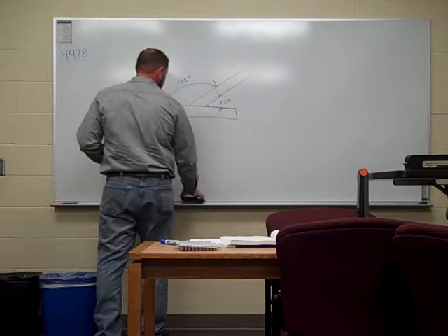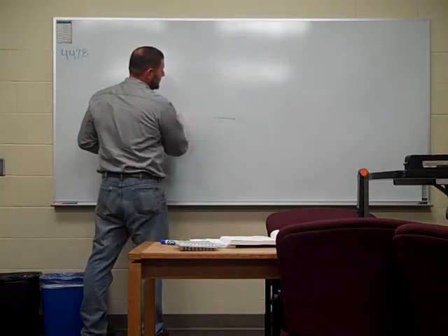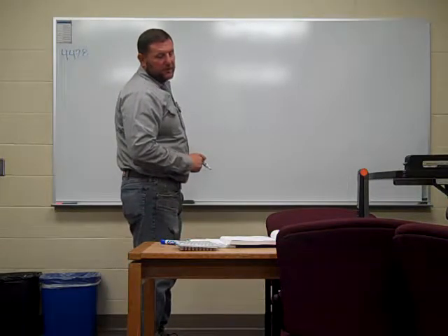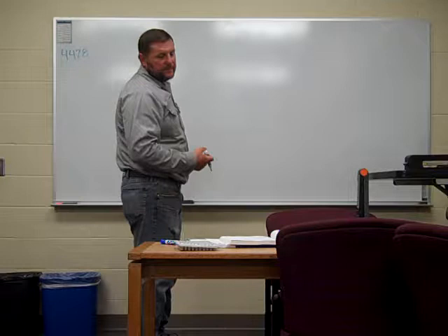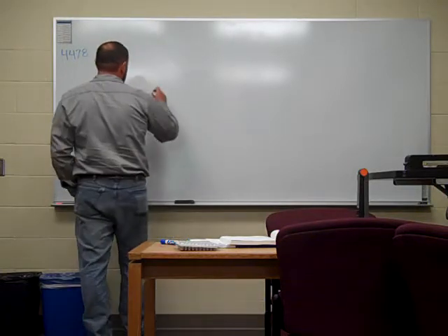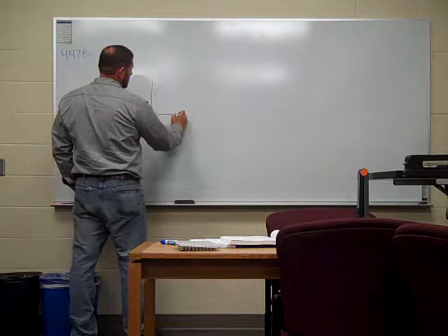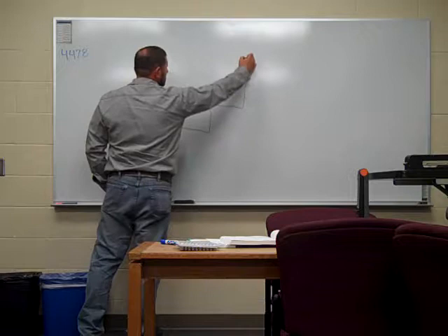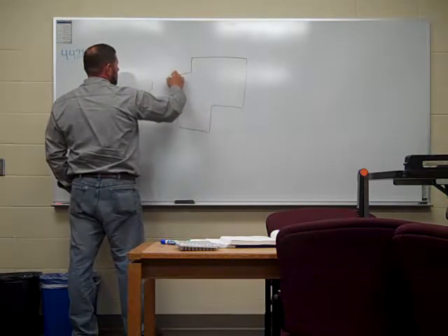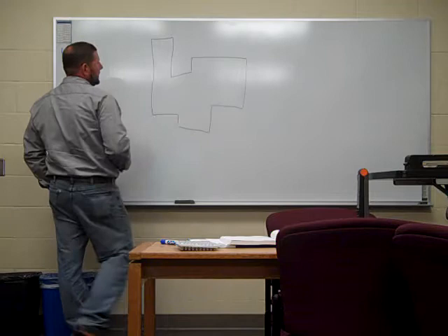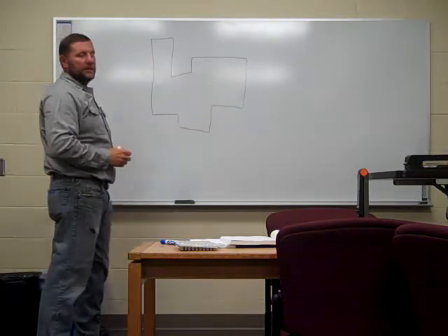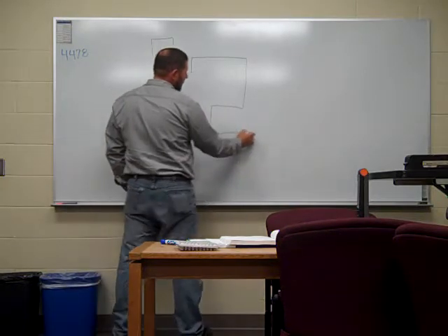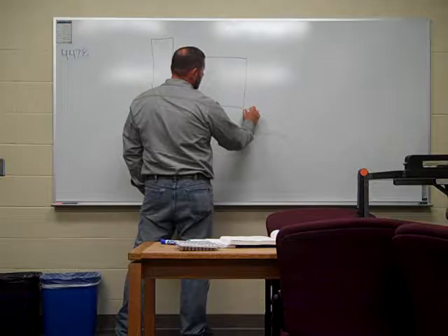So as you go down below that example on page 121, you can see they're starting to use some different styles. So this is actually what they call datum dimensioning. Now, datum dimensioning is a little bit different. I'll give you a couple different objects. A little rough shape there, but it is what it is. I'm not an artist, as you can tell. So what are they doing? They're using one reference point. So all these dimensions right here,